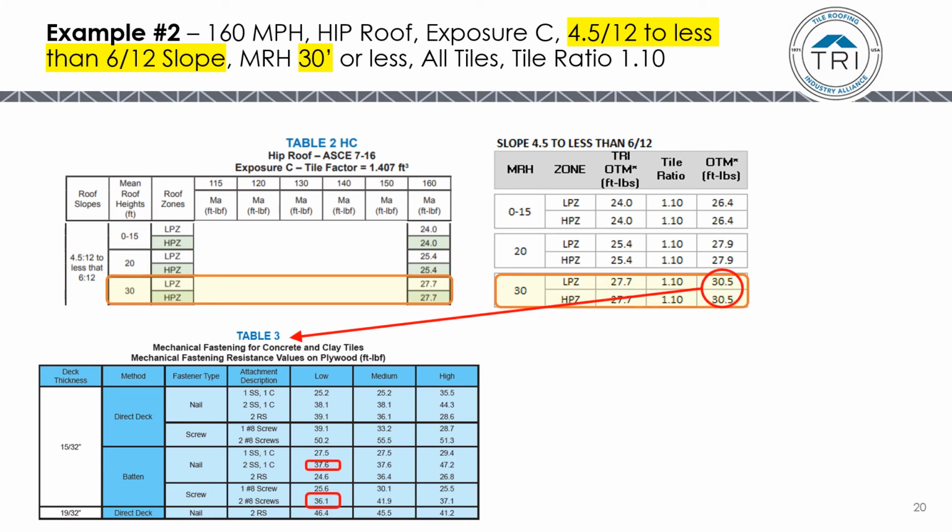And then we go over to table 3 and find out for low profile tiles, those fastening methods will work in both the LPZ and the HPZ. For the medium profile tile, those fastening methods will work. And for the high profile tile, all those exceed our design uplift moments we found from table 2.